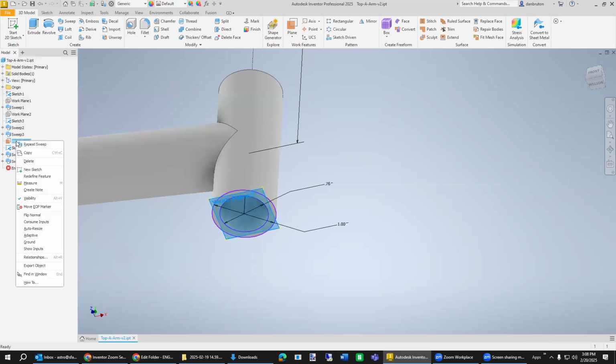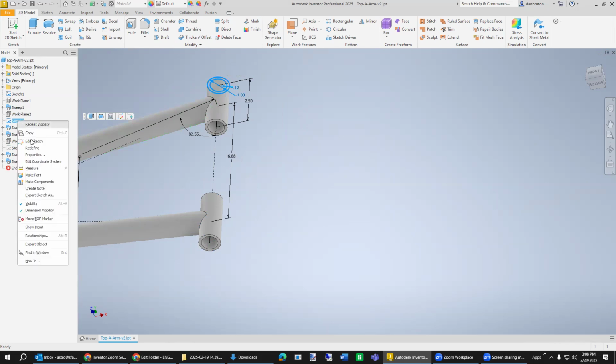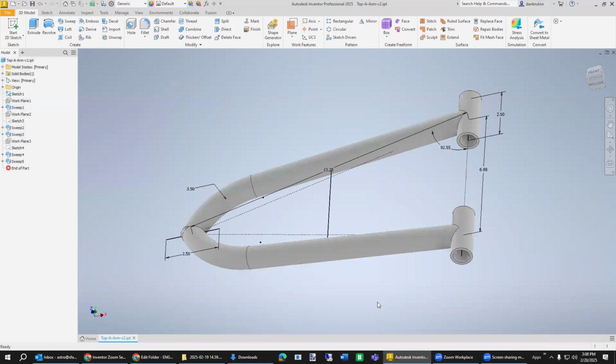Again, we can go up here, hide the working plane temporarily, and I think we can even hide those sketches as well. Is that this one? Let's see, which sketch am I looking at here? Oh, that's the sweep. So I could go up here to sketch number 4 and say, let's not make that visible, at least from this point of view. We also have one out there as well. That's probably this sketch here, and we can make that invisible as well. Making it closer to reality.